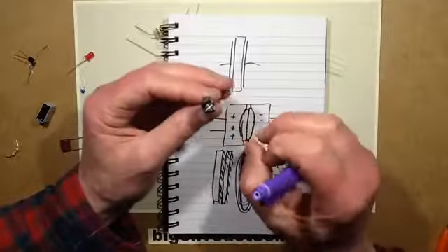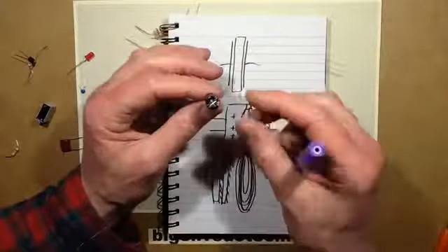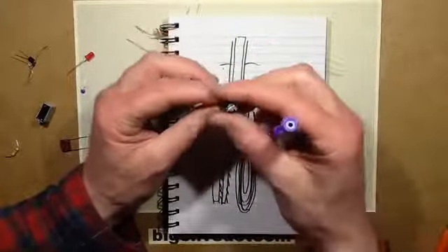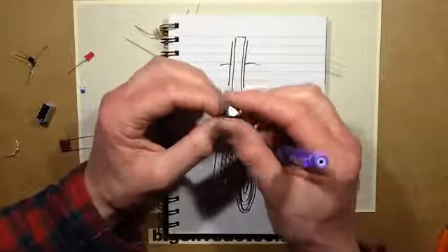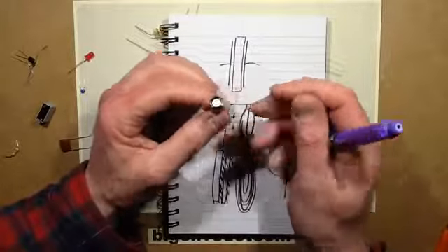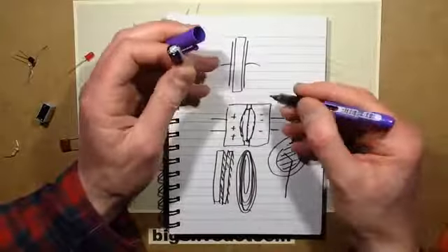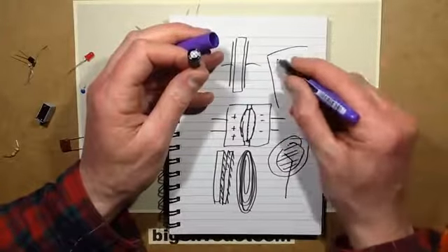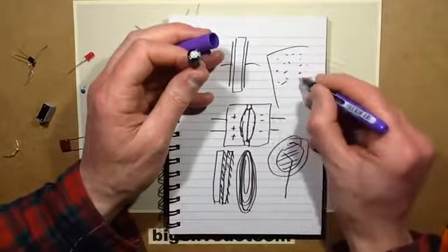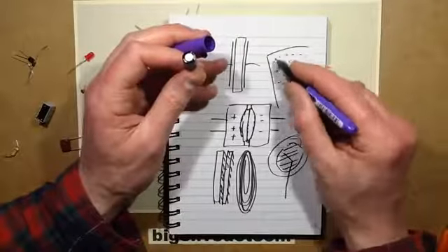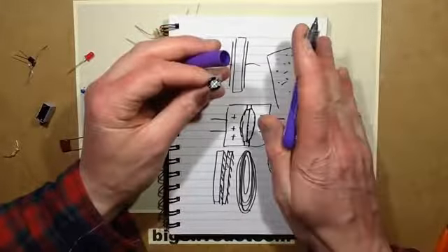That means it really is like micron thick, which means that they can get a very high capacitance in a small area. But to couple onto that surface, they have to use a liquid electrolyte, because if you looked at the foil, it would look all pitted and mottled with that oxide coating. So to get a good coupling, they use a liquid that just fills in those gaps.